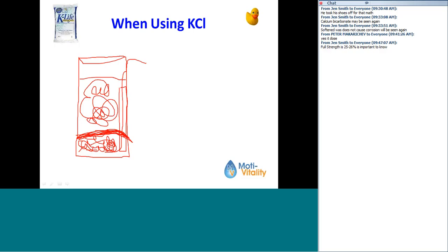So you're sucking brine, the water softener is putting the water in here, it's filling it up, it's going through its cycle and everything, but because this dome is preventing all that salt from dropping down into the water, basically you're bringing fresh water or water with hardly any salt brine into it when you're going through the regeneration process. And if you don't have a high enough percentage of brine, or salt water, if it's not making brine because the salt's not dropping down into it, then you're not going to regenerate that water softener. You're going to continually have exhausted resin in there.